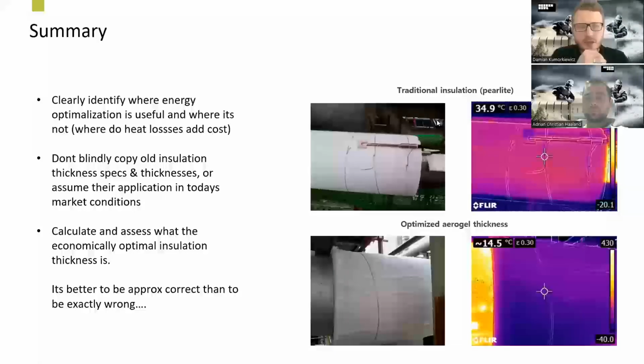Okay, and the next question: what are typical lifetimes of the insulation that you are showing us today, as per your experience? So typically for traditional insulation that over time is subjected to water under insulation and often in many cases has to be removed because of CUI, for example mineral wool, cellular glass, perlite, calcium silicates, typically everything from 5 to 15 years. Yeah, if they last more than 10 years and the operator is still comfortable with them, you are lucky.